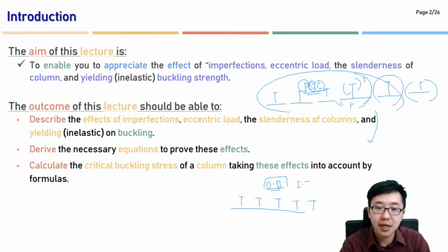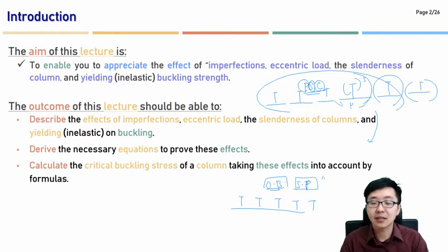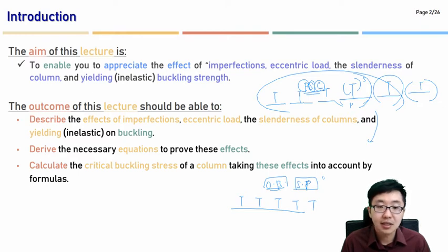So this is similar to the outer bottom, you know what I'm saying. So our stiffened panel from the ship, or side shell, deck, all those things can be calculated based on this technique. So here again, we should be able to calculate the critical buckling stress. That is the process of local strength analysis.